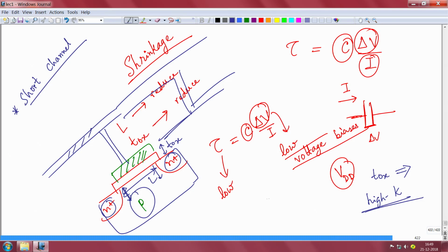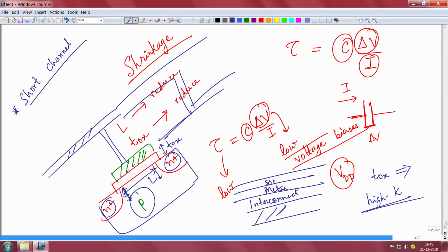When you have multiple layers, one layer would be your transistors, for example, then you have interconnect dielectric. That will be a dielectric layer that will separate, then there will be another metal line here, then again another dielectric, some silicon nitride, another metal layer here. We keep doing this for multiple layers of integration, and this interlayer dielectric or interconnect dielectric can also increase a lot of delays and slow down the circuit.